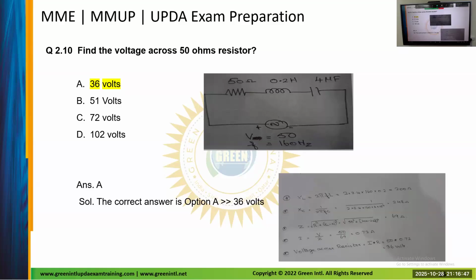Either at high speed or low speed, the ceiling fan operates with the same frequency. So the frequency remains the same. By adjusting the regulator, we increase or decrease the voltage. So the frequency is constant and the voltage is changed.